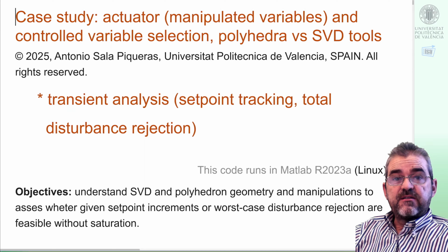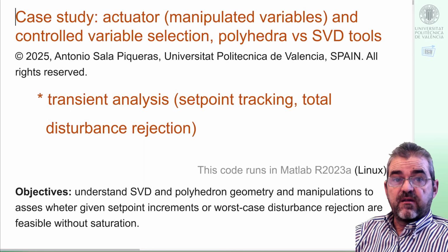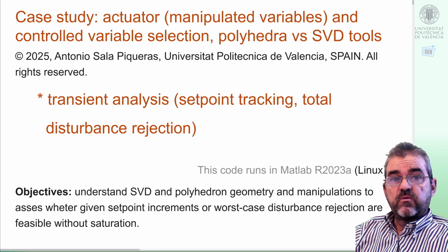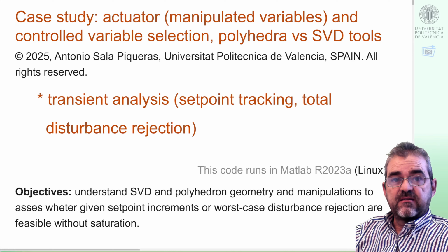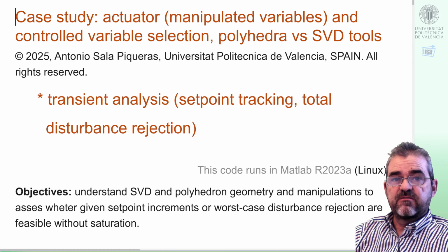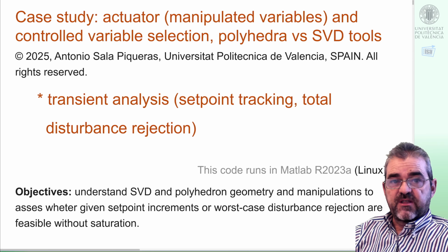I'm Sala, and in this video we are going to end the case study on manipulated and controlled variable selection. In previous videos, we discussed steady-state analysis with both SVD and polyhedron geometry, analyzing setpoint tracking, total disturbance rejection, and partial disturbance rejection.